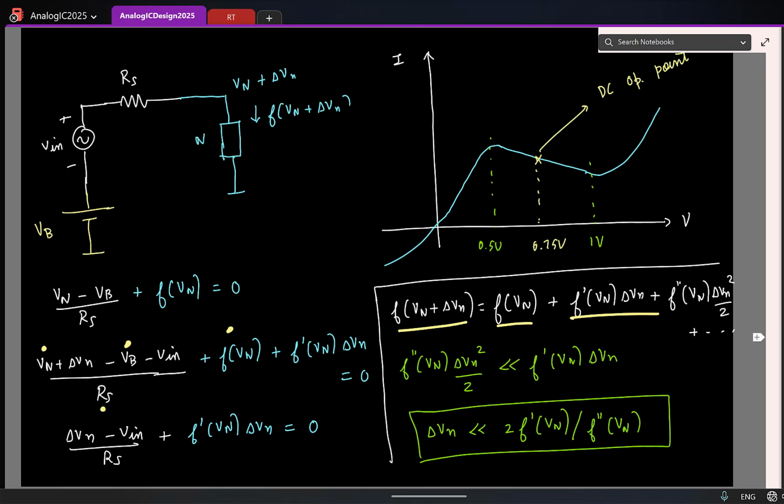Okay. So yeah, one jargon: this is what we call a one port device. By port, we say that any pair of terminals we call a port. Here I have two terminals, so we call this a one port device. And so we saw how to make an amplifier with a one port device. If the one port device has to act like an amplifier, it should have some kind of a negative slope in its nonlinear characteristic.